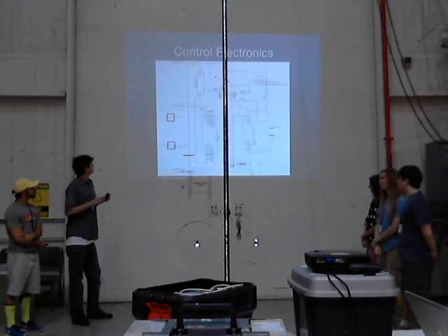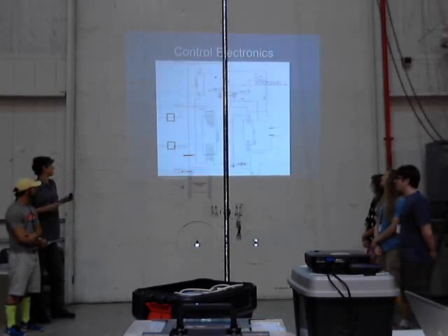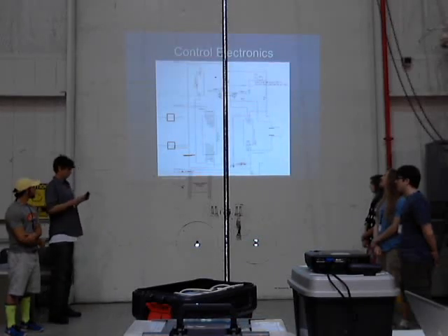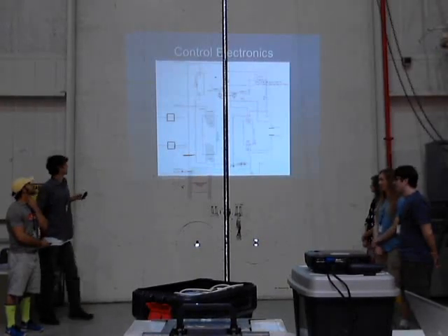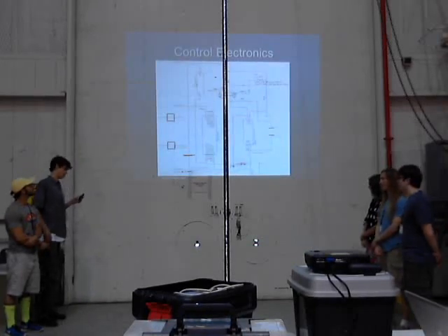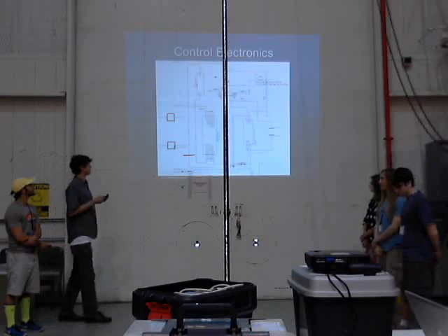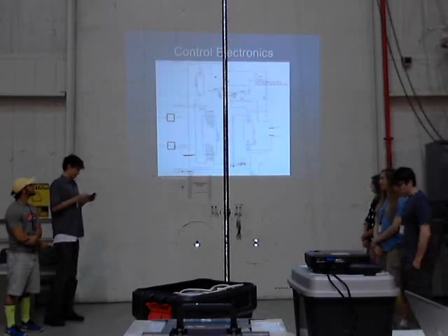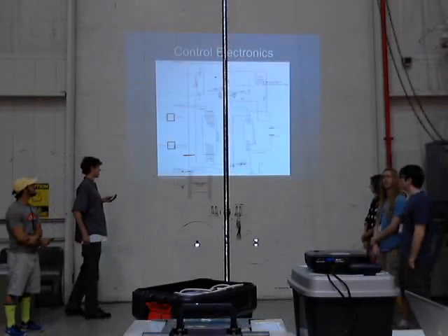And so we start coming in, and our input circuitry consists of a low leakage operational amplifier, which acts as a buffer, the LM6042, and two JFETs allow the switch to reset.